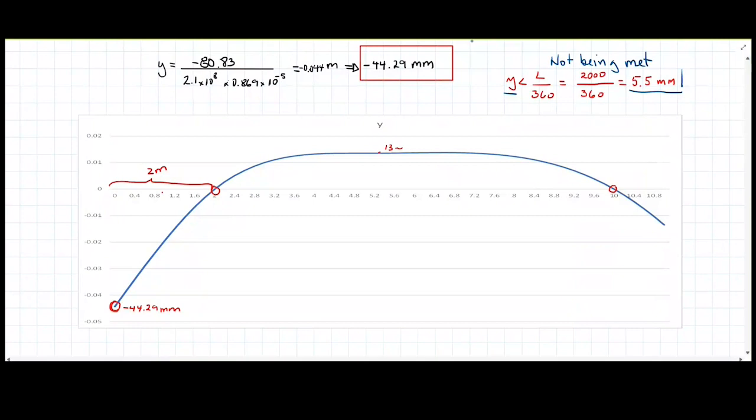What does it mean? That the profile you have just chosen does not do the work according to specifications related to deformation. What should I do? Should I modify something? Well, you don't have to do any other calculations besides selecting a different profile, as we mentioned, and changing this term with the inertia properties of the new profile you are choosing, which most likely will be the next largest one, and then compare if this is going to be met or not.